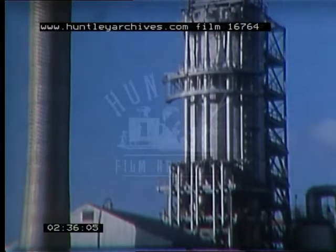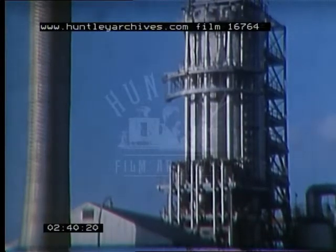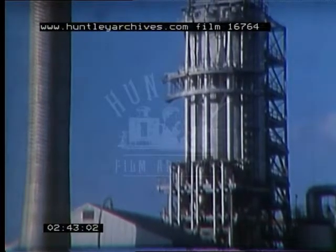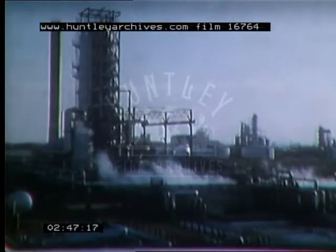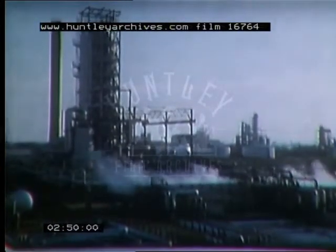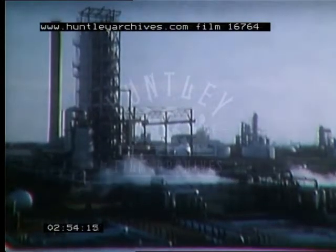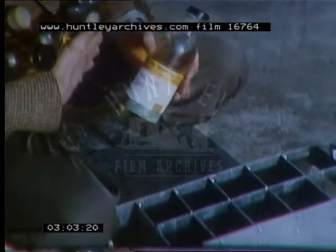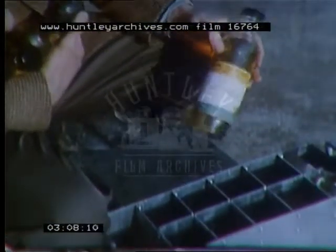There are 3 ejectors at the top of the tower and 2 more sets of 3 about halfway down. They are arranged in 3 parallel series. This vacuum distillation unit serves the lubricating oil refinery, and it is required to produce a series of cuts. In the refinery, regular samples are taken to check the quality of the products. Here we can compare the incoming atmospheric residue with the products of the vacuum unit. These are the lightest, a vacuum gas oil, as an overhead product, and 4 waxy distillate side cuts.